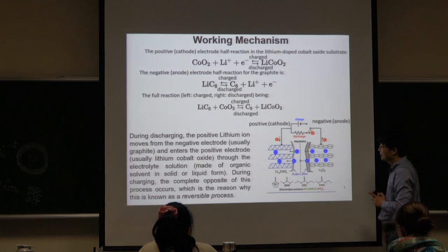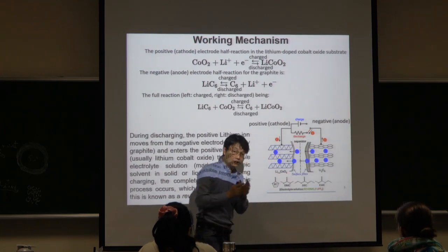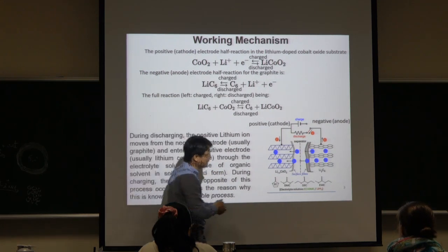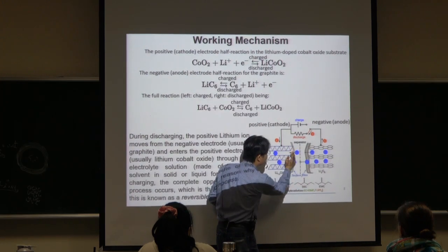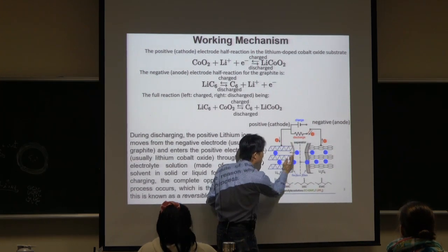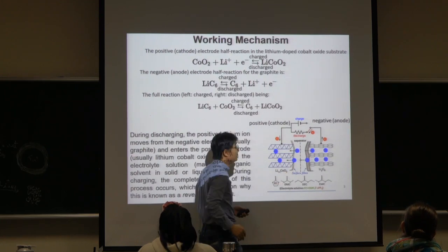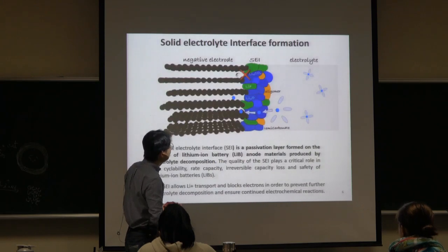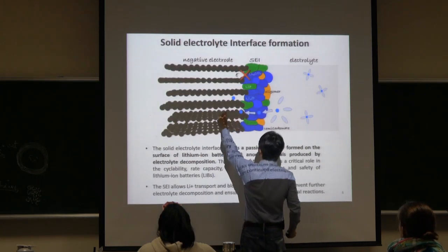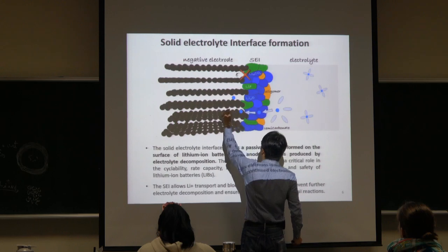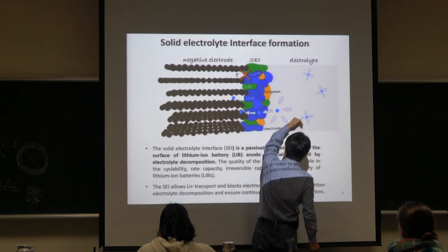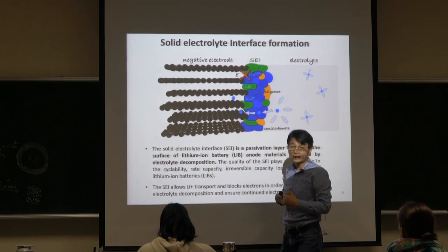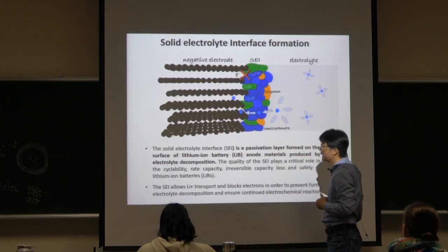But because you know there's SEI formation, right? SEI is a surface cover layer. Here we have explained, this SEI becomes a barrier that makes the lithium unable to transfer out, right? So therefore, the Coulombic efficiency will go down, will be reduced.